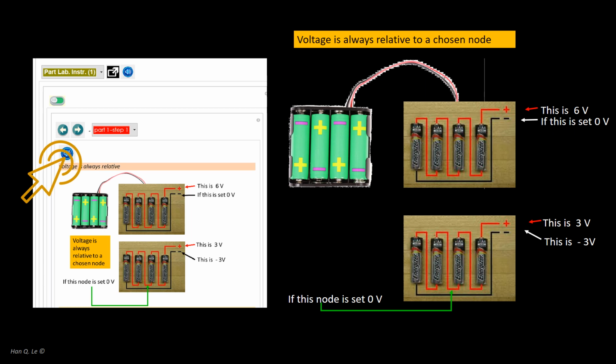Voltage is always relative with each other. Swap two terminals of a voltmeter that measures, say a battery, we will get an opposite sign value. If there are several independent source voltages, one can join them together to add, subtract, or make any combination thereof. One can choose an arbitrary node as the 0-volt reference to create new voltage values.